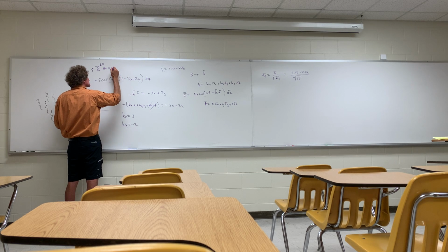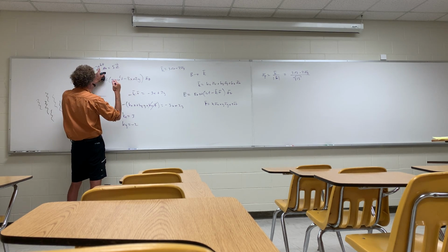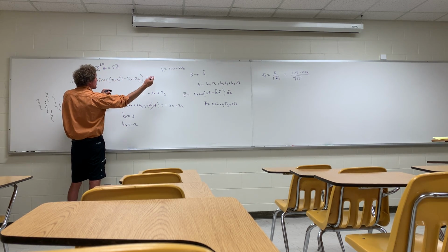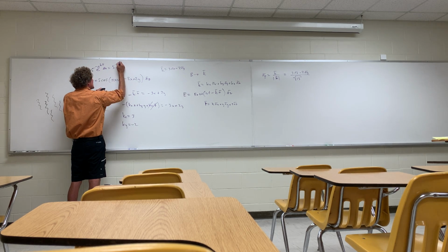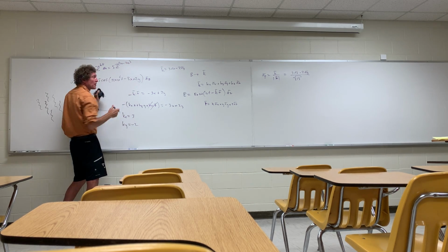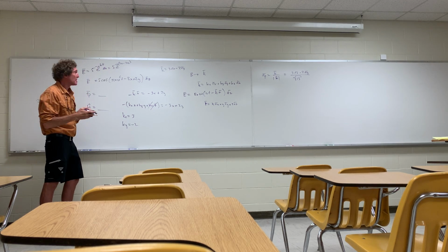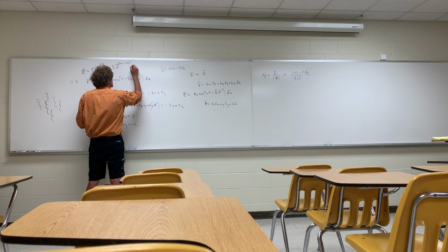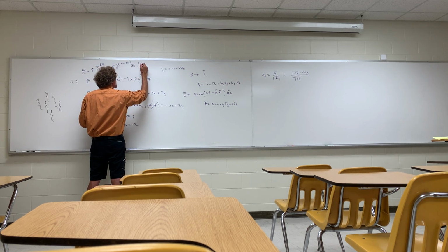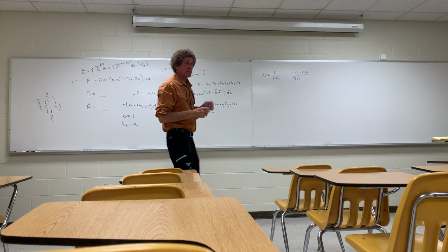Now we know that that's going to be 5 times e to the minus j. Here, I'll do the dot product. I'll just take k dot r right out in front. So I have minus j, and it's going to be 3x minus 2y. Do y'all follow me on that? I'm just putting k dot r up there, and it would be in the az direction. The units are volts per meter, I believe, for this one. So that would be the phasor form.